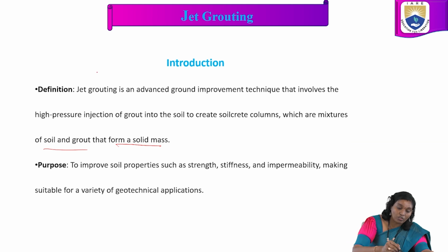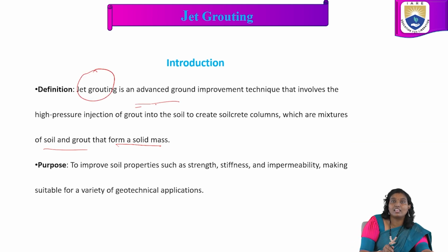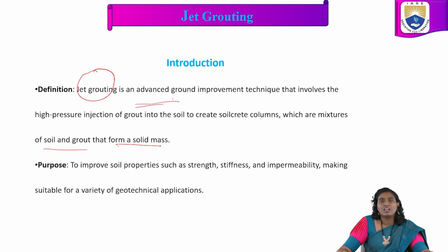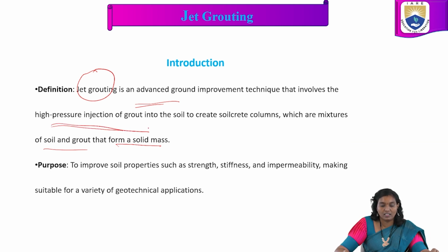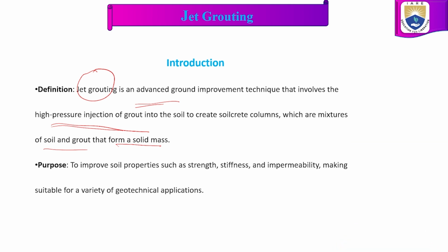Coming to jet grouting, it is the advanced technique we use for the improvement of the soil. In this, we inject high pressure grout into the soil to create soilcrete columns, which are mixtures of soil as well as grout that form a solid mass.